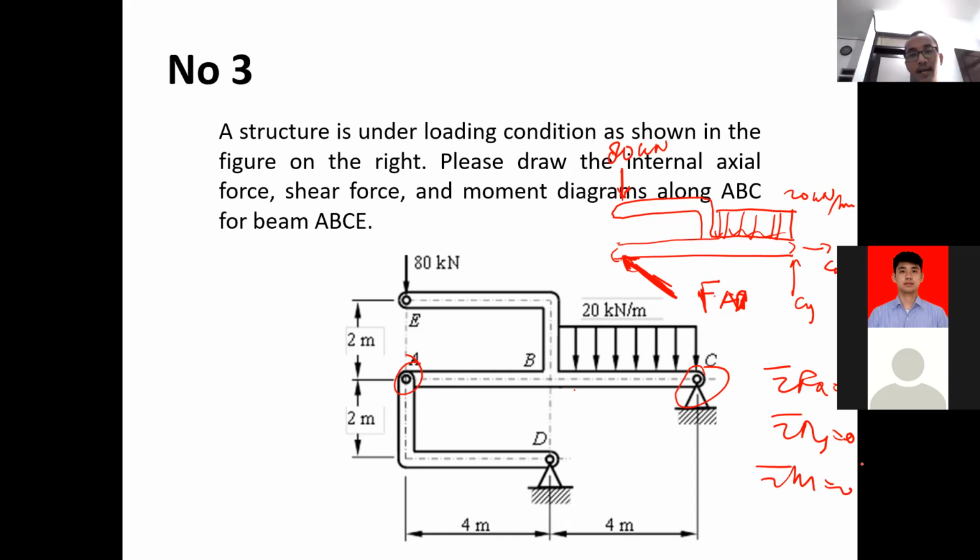When you find that there is a two force member, then treat it as a two force member. So you just replace the member with the force representing the two force member, because for a two force member, the force is always from one end to the other end, right? Like that. You get it, Alberto? Yes, sir.